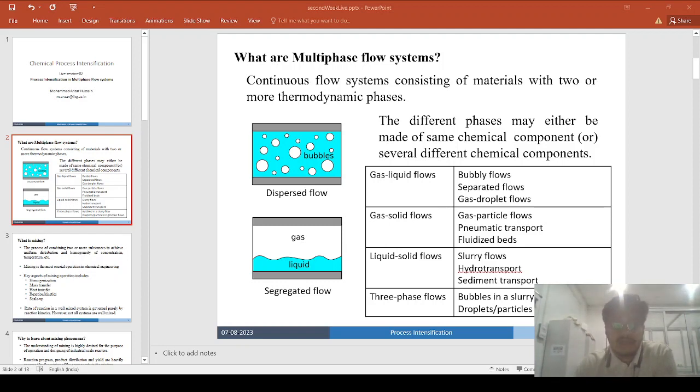You might notice that we are not mentioning the involvement of solid particles as of yet, because due to the very small constricted size, particles generally tend to coagulate, and coagulated particles may then jam the microreactor, so the flow will not happen. So typically the applications performed in the microreactor environment are gas-liquid or liquid-liquid multi-phase flow systems only. Very rarely are solids used here.